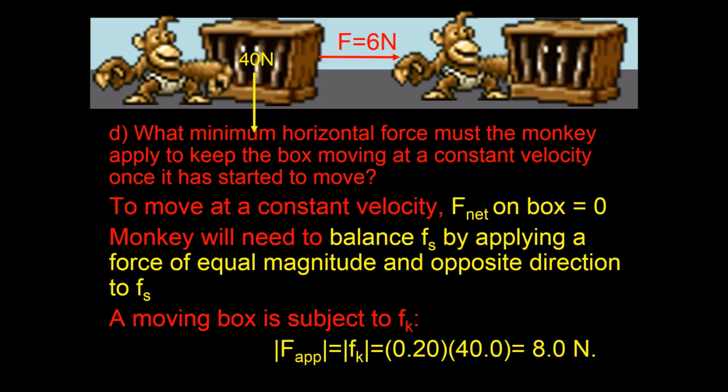So those are two situations of looking at how we can treat forces, driving forces versus frictional forces. And it's very important to remember the couple of occasions where you can really calculate out your forces. One of them being the point at which the block slips. What force of friction do you need to overcome with a driving force to move your object? The other being, if an object is moving with constant velocity, your accelerations are going to cancel.